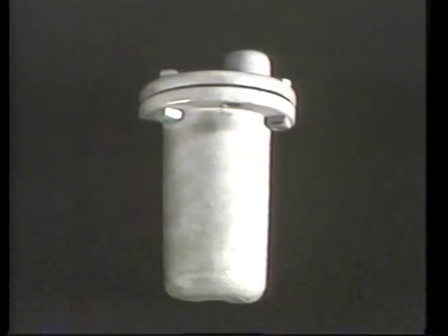Second, traps can respond to a difference in density. Steam is less dense than condensate, and traps that use a density differential to separate steam and condensate are called mechanical traps. The most common mechanical traps are the float trap and the inverted bucket trap. Of course, since the densities of air and steam are very close to one another, mechanical traps usually require a second method of separating air from steam. Now, this second method is often a thermostatic device.